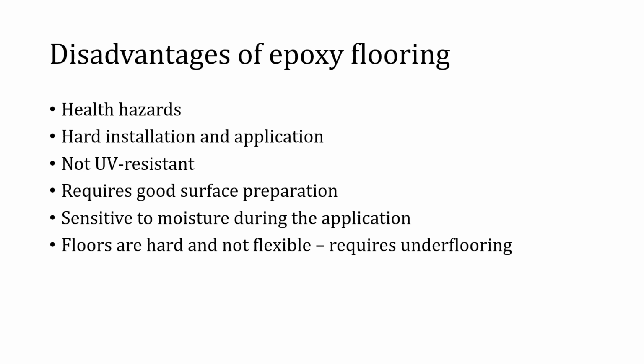Most prominently solvent-based epoxy floorings. However, modern epoxy flooring is very safe. The only danger that comes with epoxy is during installation or if it is incorrectly applied. During the installation of epoxy, the installer must wear a respirator to apply the finish. The area will need to be well ventilated.